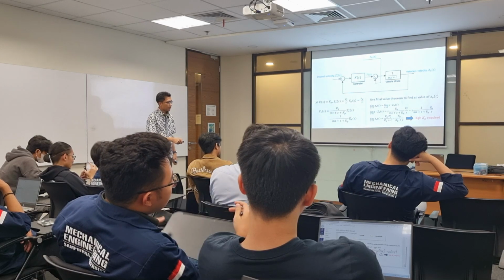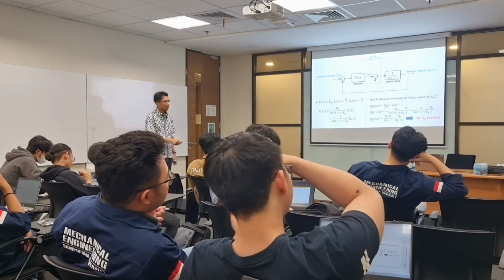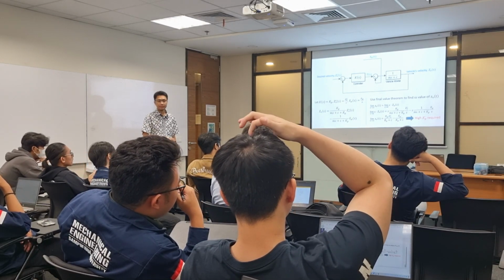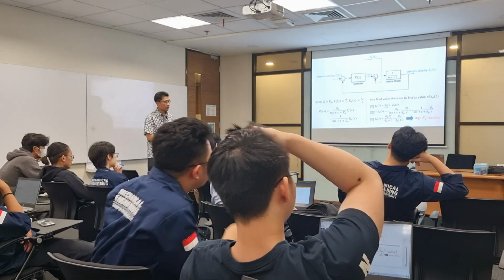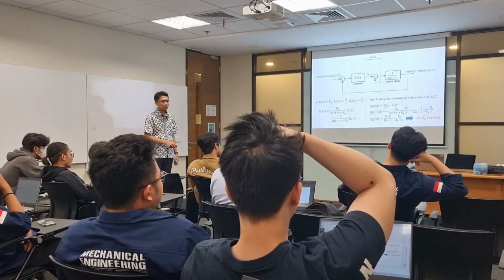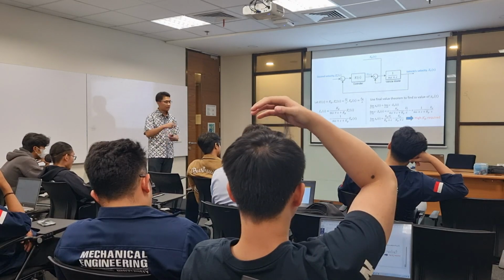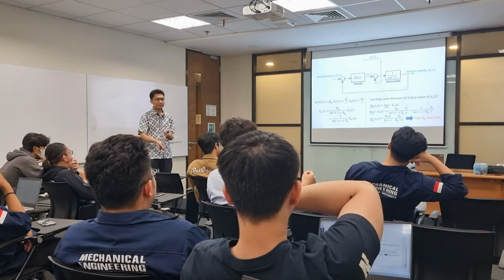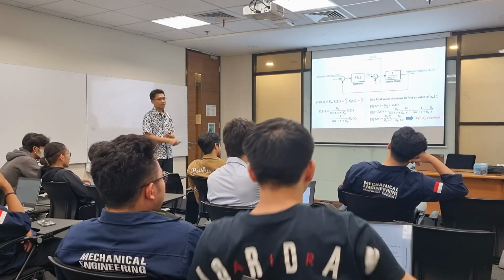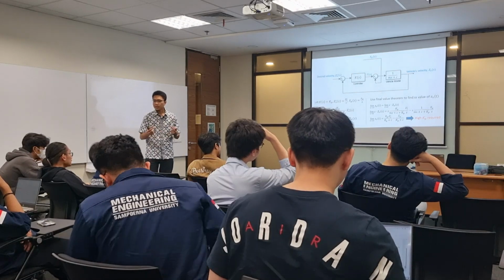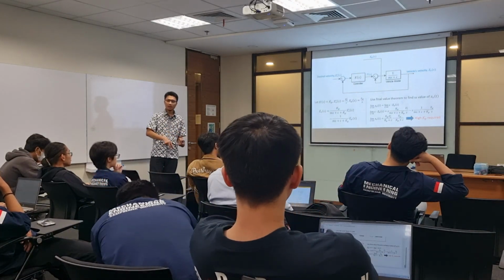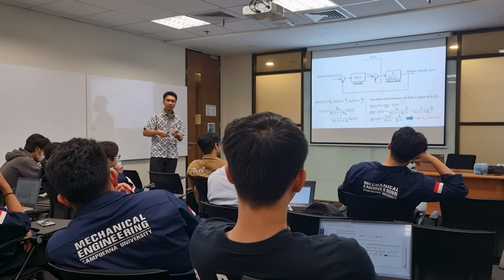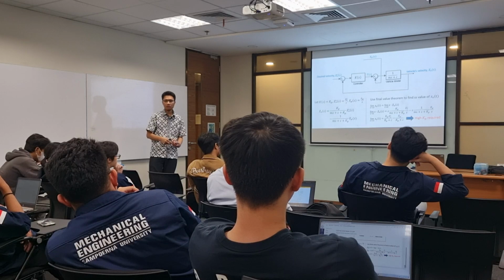Having seen the last line here, we can see that the effect of FW, or the disturbance, is over here, yeah, the second term. And the second term will be small if we set the Kp to be high. But there is a limit on the Kp that we can put into the system because Kp is related directly to the traction. There is a limit on how big an engine we can put into the car, right? That's the limit. And also there is a limit on how much traction you can put into the road from the tire.